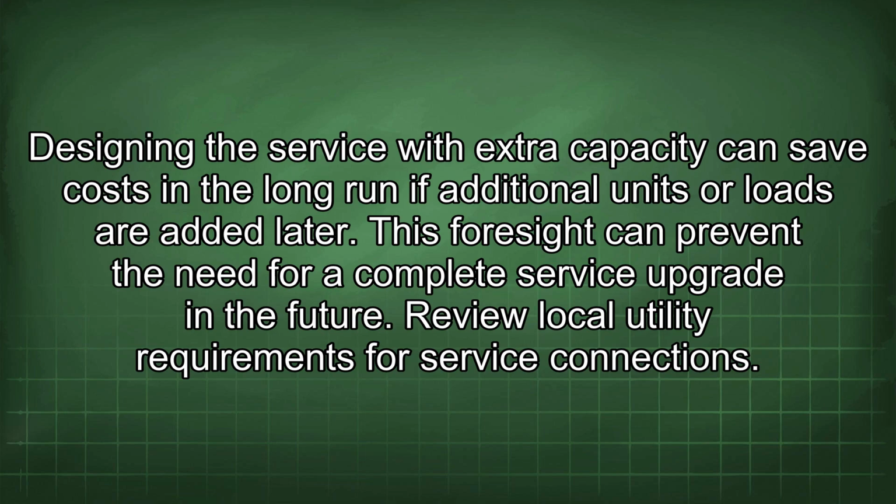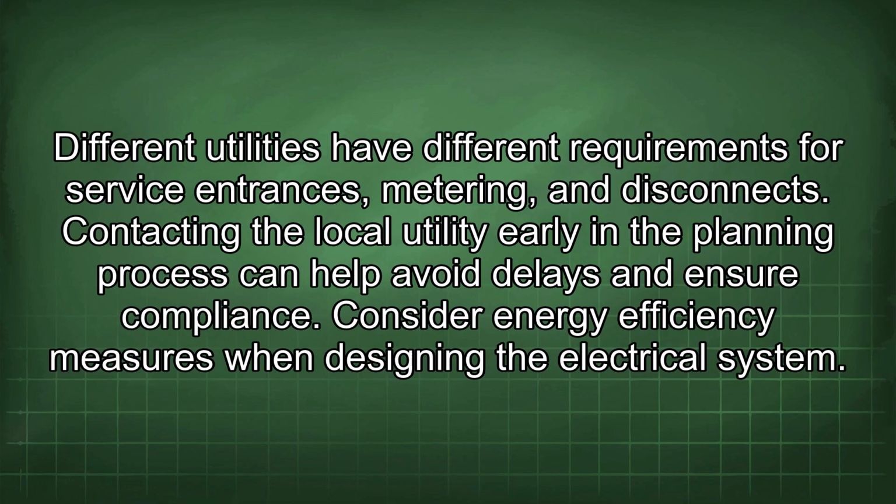Review local utility requirements for service connections. Different utilities have different requirements for service entrances, metering, and disconnects. Contacting the local utility early in the planning process can help avoid delays and ensure compliance.